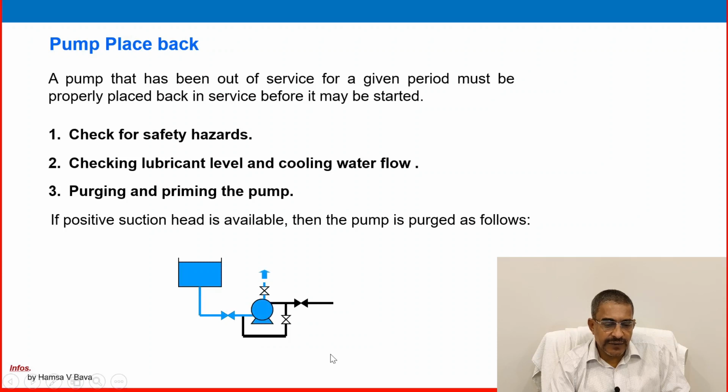Imagine it is a hydrocarbon liquid: slightly it will come up, and you can see it slowly coming into this area. Then close that valve and open the recycle line until it is full. So now the pump is fully filled with the hydrocarbon liquid, and no air, hydrocarbon gas or unwanted material is trapped inside.